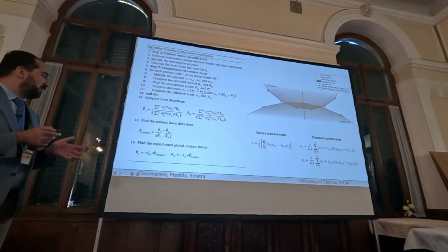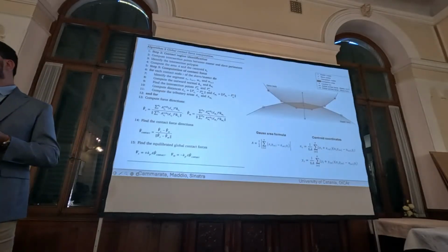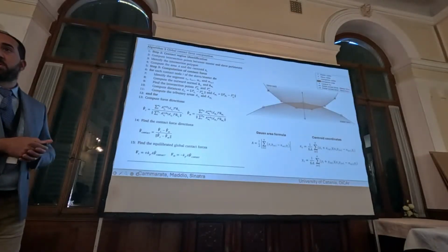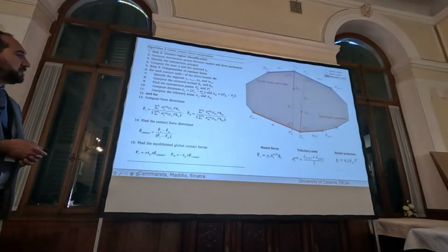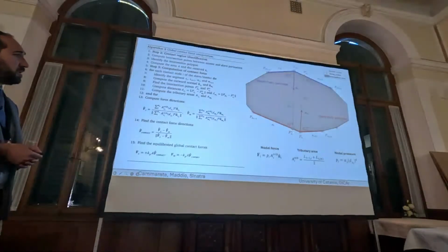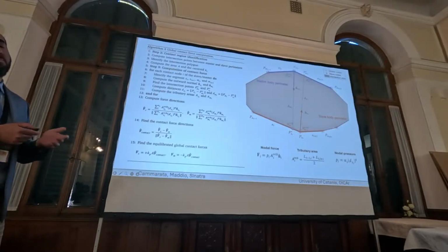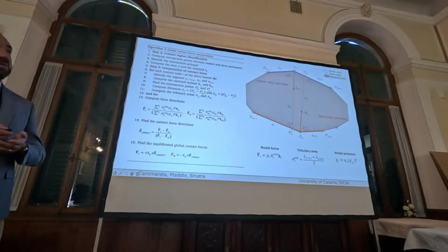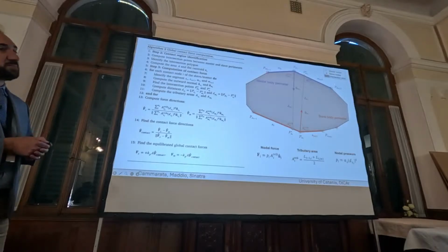the absolute value of the contact force is a penalty formula. So we have a penalty coefficient that multiplies this area. What about the direction? The direction is more complicated because in that case, we have to, for each point of the first body that I call slave, but it is symmetrical, so we can switch the bodies. And so this is the slave, the red one is the slave, and this is the master.